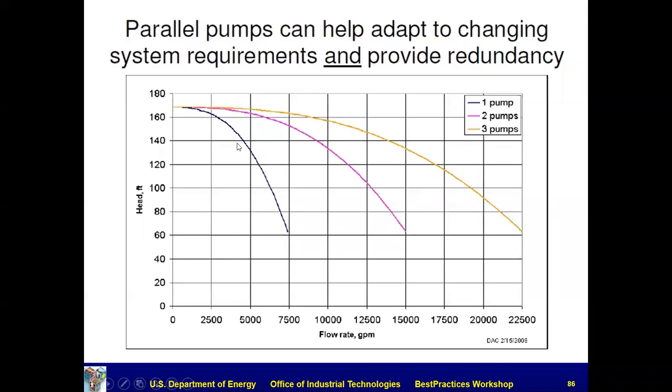I take this single pump flow at whatever head and multiply by 3. And so then that takes me right out to here. And if I'm doing 4, I multiply it by 4, and I come out to here, and 5, I come out to here, and 6, I come out to here. And that just gives me 1 point on each one of those equivalent pump curves.